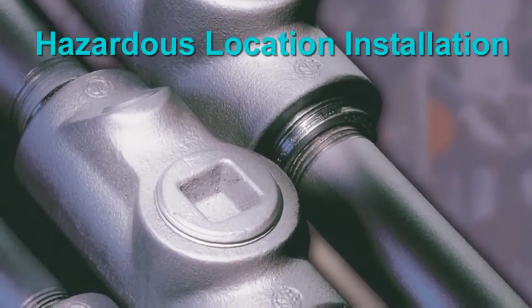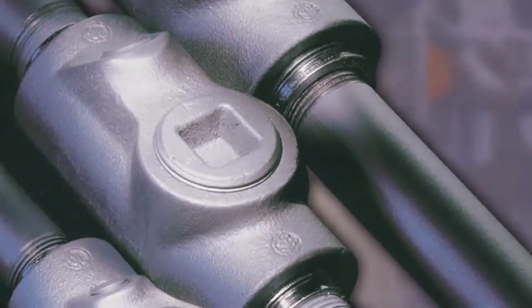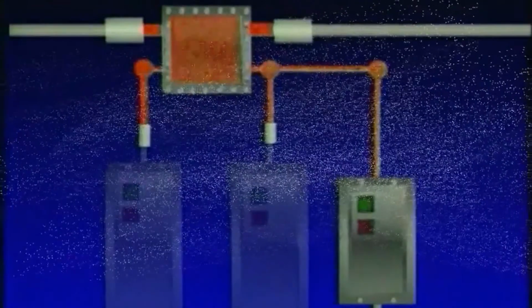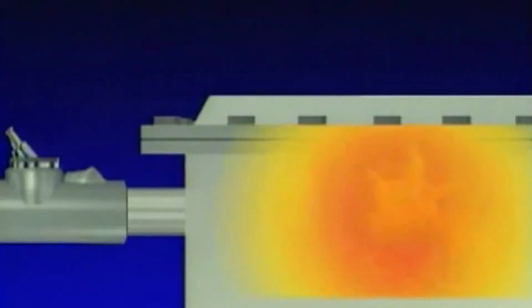Proper installation of hazardous location equipment calls for the use of seals. Special fittings are required to keep hot gases from traveling through the conduit system, igniting other areas in the event of an internal explosion. They are also needed in certain situations to keep flammable dust from entering the dust ignition-proof enclosures through the conduit. When arcs and sparks cause ignition of flammable gases and vapors, the equipment contains the explosion and vents only cool gases into the surrounding hazardous area.